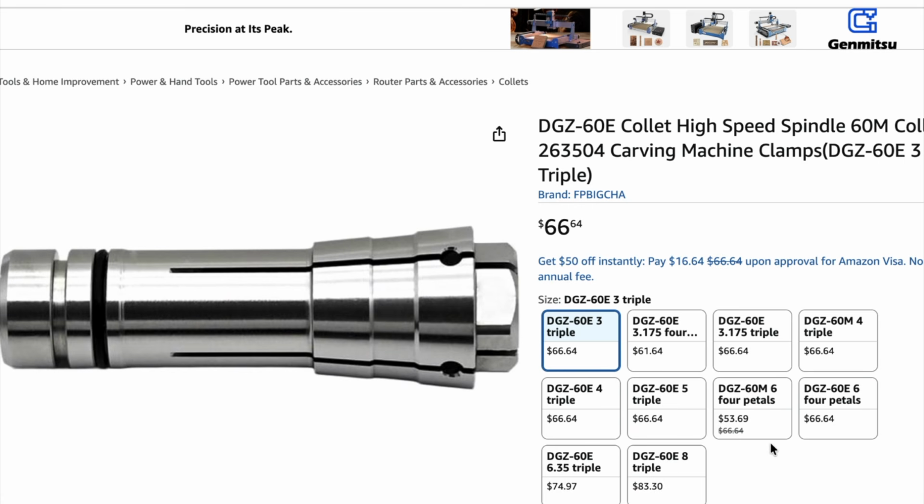You're a beginner. Also, we're going to go shopping on Amazon. Now I know you're going to say, Amazon tools are junk. You should treat these beginner tools as a disposable list of tools. You're going to break tools. You're going to wear tools out. This is to get you started on the lowest budget possible. If you go out and buy a $60 1/8 inch end mill and break it the first time it touches the part, you're going to be pretty sick. And the reality is, you're going to break it anyway. So you might as well buy cheap tools.